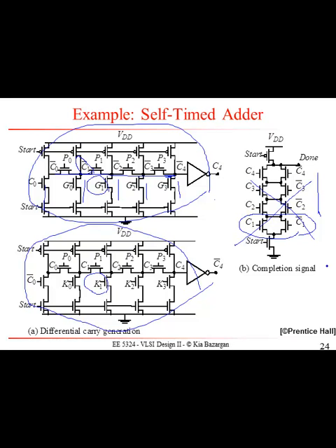All right, now I assume that you got it, because it could be the case that for one particular input combination, you could have a kill right here, which means C4 is going to be generated immediately, but you might be in propagate mode, which means your C3 is going to be generated much later than your C4. So the answer is you cannot get rid of these guys. You do need every single one of them to make sure that all your carry signals from this block are ready before you can proceed to the next step.